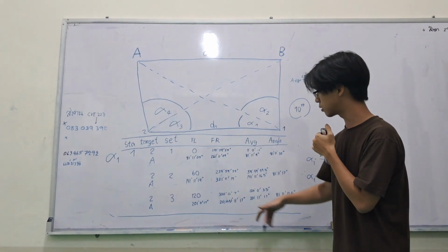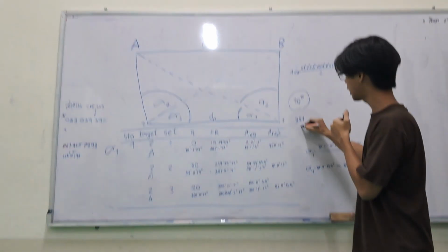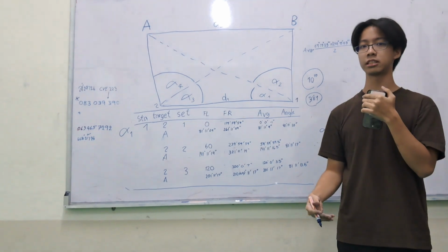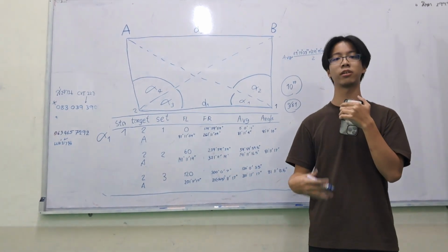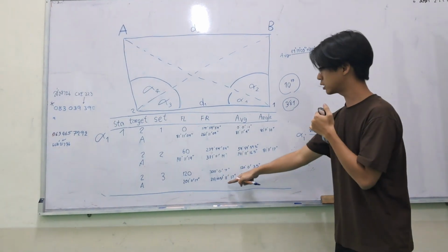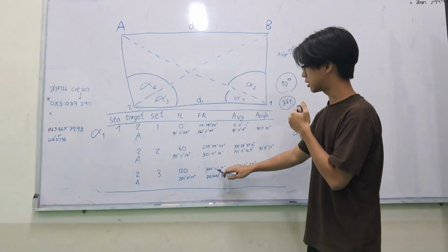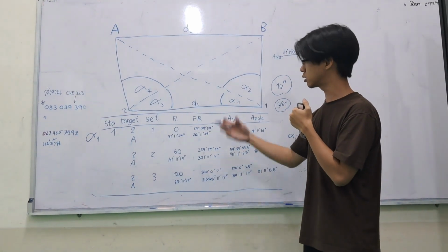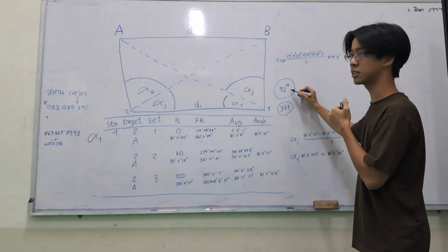Turning clockwise, this one should be 201 plus 180. It should be 381. But the total station is gonna show you 21 degree because it cannot show an angle that exceeds 360 degree. So when you record, you need to note yourself that this one is not actually 21. It's 360 plus 21. When you turn back, it should be 300 degree, which is 180 degree plus 120 degree. For the error, you need to check that everything does not exceed 10 seconds.